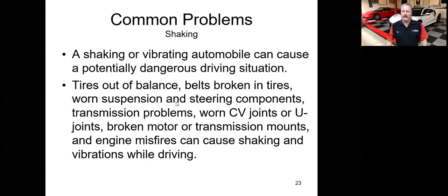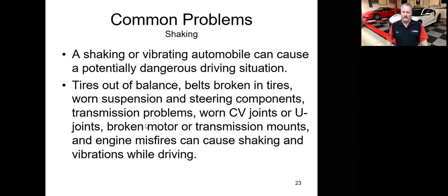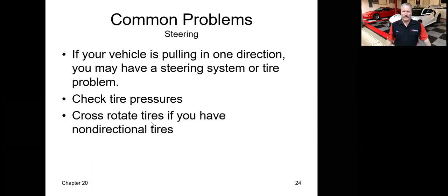Only when you apply the brake pedal, if it shakes, that would be a rotor problem. Right? Those are two really common ones. If your vehicle is pulling in one direction while you're going down the road and your foot's not on the brake pedal, check your tire pressure. Could have a low left front or right front tire.